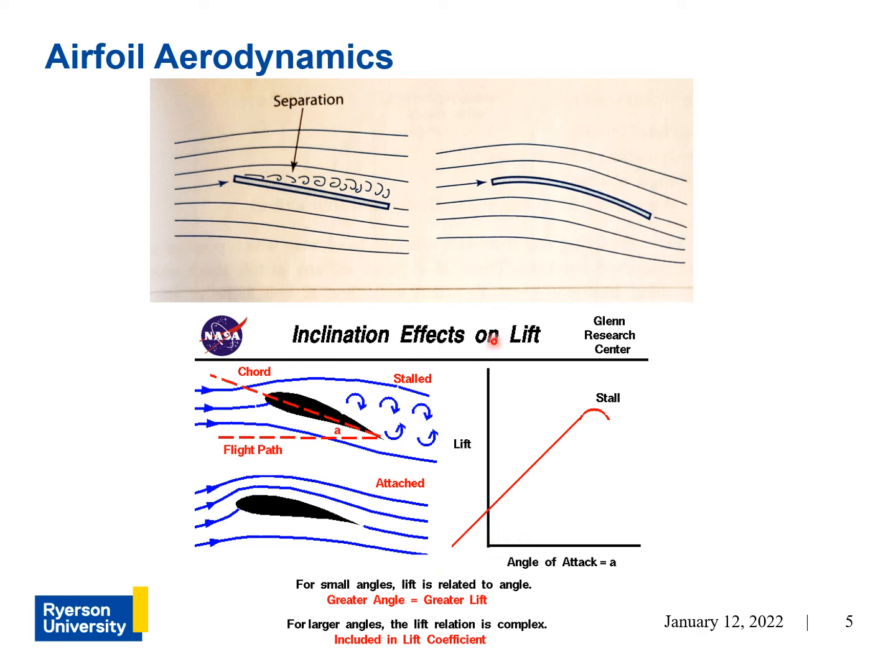And I suppose the effect of having a camber on an airfoil versus having no camber is essentially just shifting the curve upward, right? So if the lift curve for this plate were to be shown, it would probably look like this. And because it's symmetric, and of course this region here is the stall region.